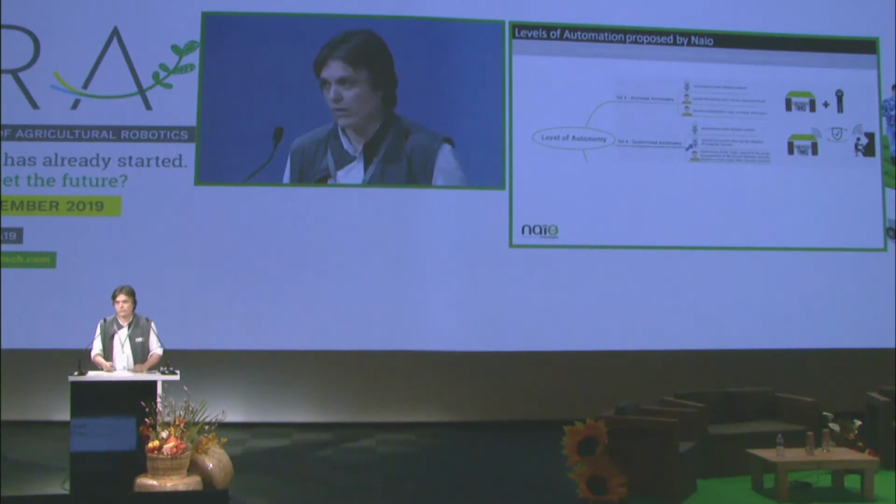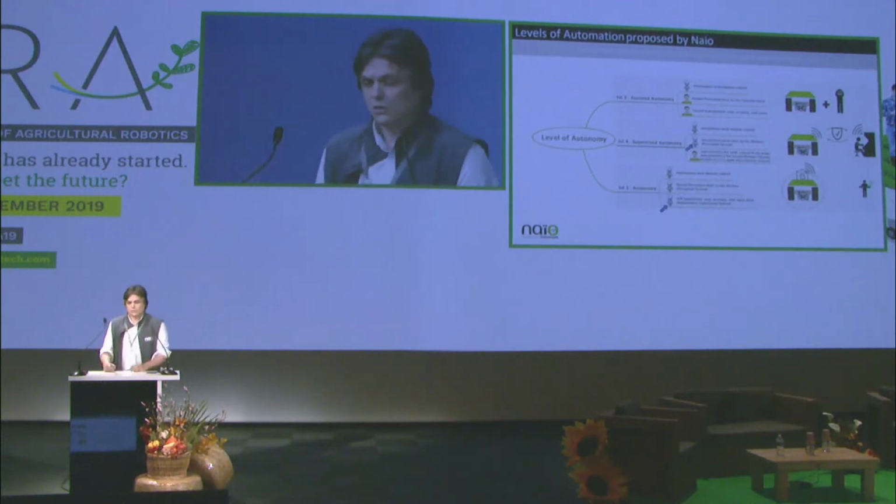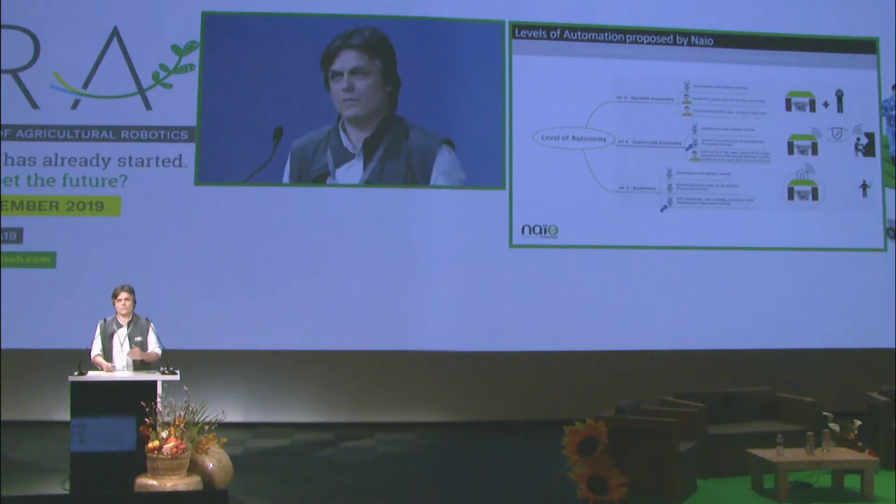And at level 5, what we call autonomy, full autonomy for some people, the machine is able to do all of these jobs alone. So autonomous work, but also perceiving if there is any obstacle in the vicinity of the machine. And there is also a supervisory system which is able to take complex decisions, especially to decide to start again when you have removed or dealt with a hazardous situation.